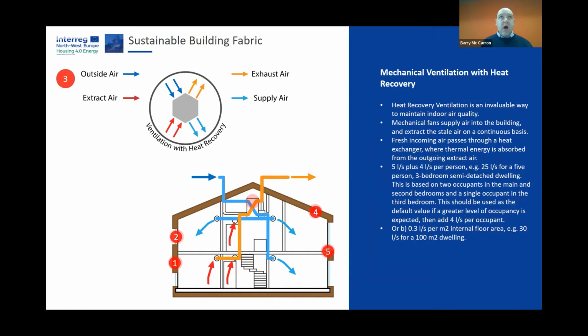It's quite common to have your indoor air quality level in a passive house sitting at around 600, 800 CO2, even with the occupancy of the house in all the various rooms, and that is excellent because it's not over the critical figure of 1,000.